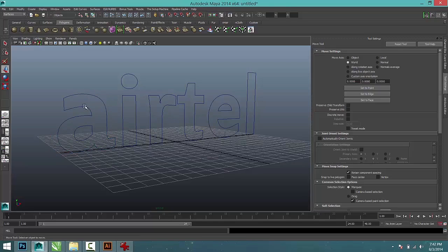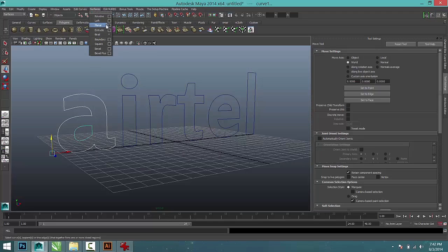So I select for the A, I select the outer curve like so, and then select this center curve. If I don't do that, I run the risk of just running the plane surface through without the cutout for this space. All right, so while doing this, it recognizes that there are actually two curves and only places the surface within the areas that have been selected. So I come to surface, all right, and click planar.